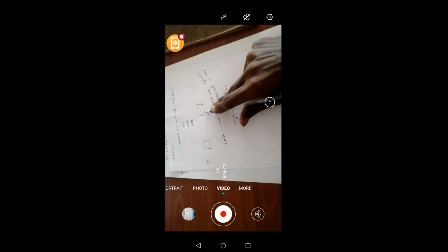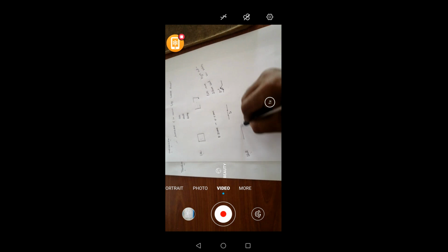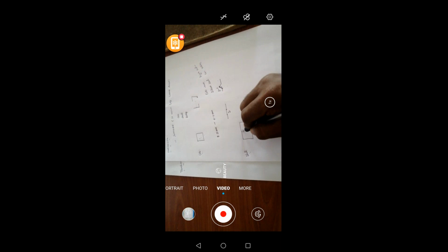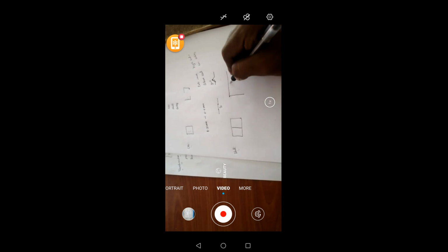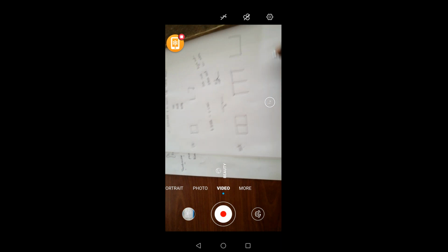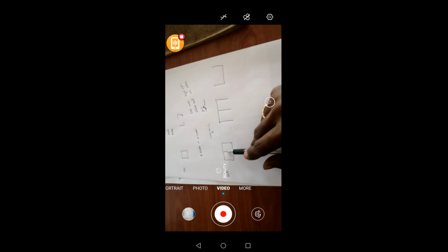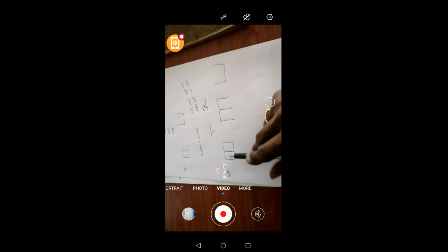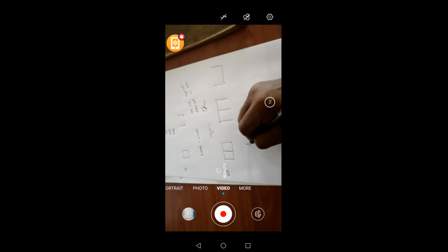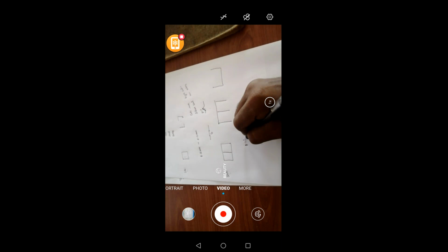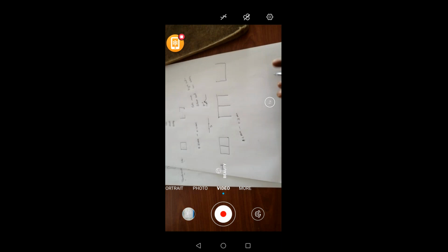Now let us see the shell type. For the shell type transformer, the final shape of the shell is like this. They connect E shape and U shape, so these are the two shapes. They cut the plates and after that they are bunched together. Finally, we will get this shape like this. And here the thickness of the lamination, the thickness of the metal, is 0.2 mm to 0.35 mm. This is the thickness for the shell type transformer.